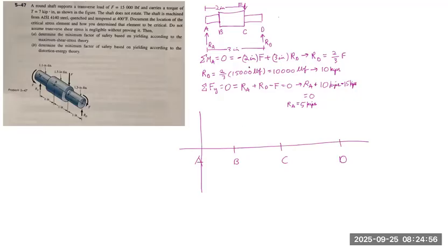So as we see over here, the reaction force at A, which we begin, is 5 kips. So it will be positive 5 kips. And this is in kips, and this is position, X. Let's call it X. So the 5 kips will extend from A to B, or rather A to C, sorry, because the reaction force is only here, and then we don't have another force until point C. So it will go all the way to C.